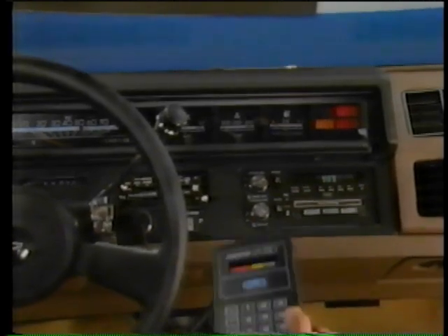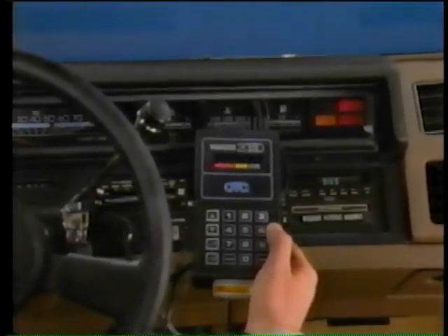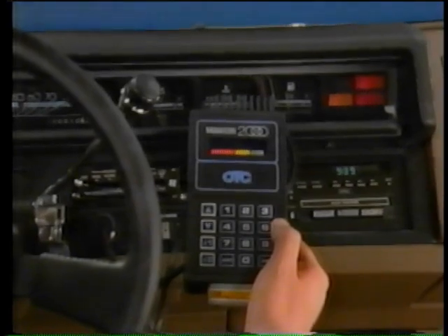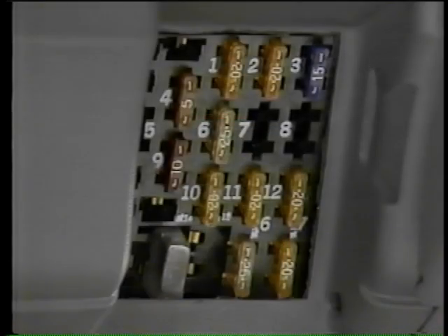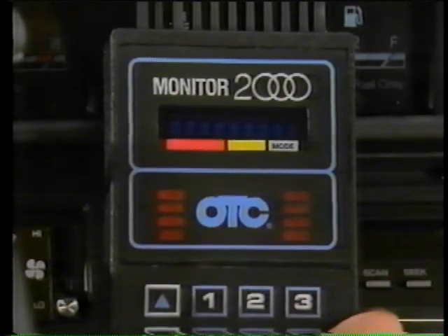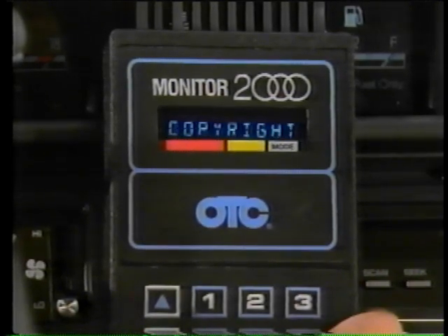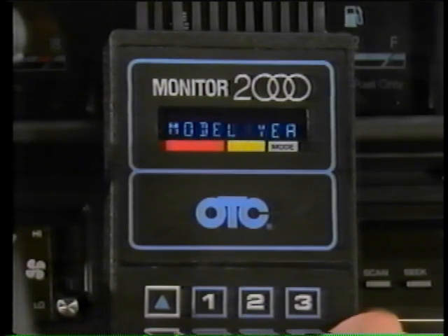The scan tool display should light up if it's getting adequate voltage. If it doesn't light up, make sure the connection at the cigarette lighter is good. If this isn't the problem, check the condition of the lighter fuse and make sure the battery voltage is at least 11 volts. Scan tools require a minimum voltage to operate correctly. You could also test the tool on another vehicle. When the scan tool is powered up, it will run a bulb check of sorts to ensure that all the LEDs and characters are working properly.